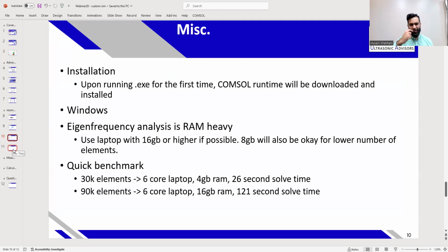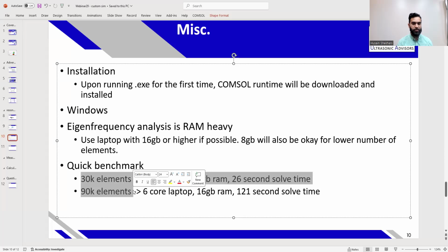I also wanted to mention the other nice thing about doing a segmented, or quarter model: you cut the model so that you can see the mesh on the inside. I don't have different mesh analysis methods. You're more going to need to take a look at the model to see if it has the elements in the right places at this point. But usually for modal analysis, we're not as concerned. Typically convergence, like I did some convergence, these two simulations had pretty much the same frequency.